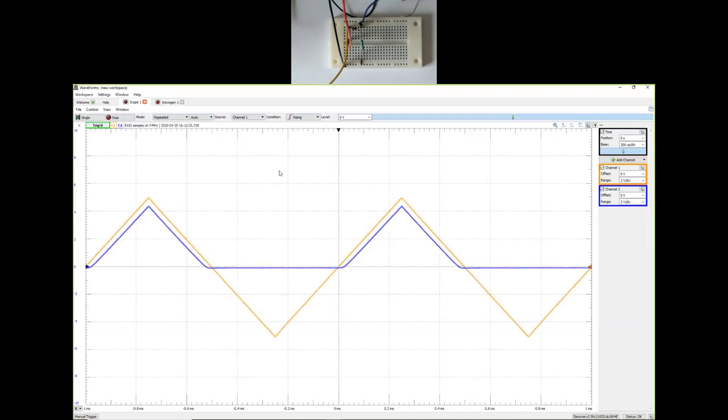So the moment I start the scope, I can see two lines, channel 1 and channel 2. I'm going to remove noise on both of them, and I'm going to make the plot width thicker. So for example, I can go to 3 here, and the blue line is the rectified output, I should say half wave rectified output, and clearly you can see that the average of the orange line, the source, is 0, but the average or the mean value of the blue line is positive.